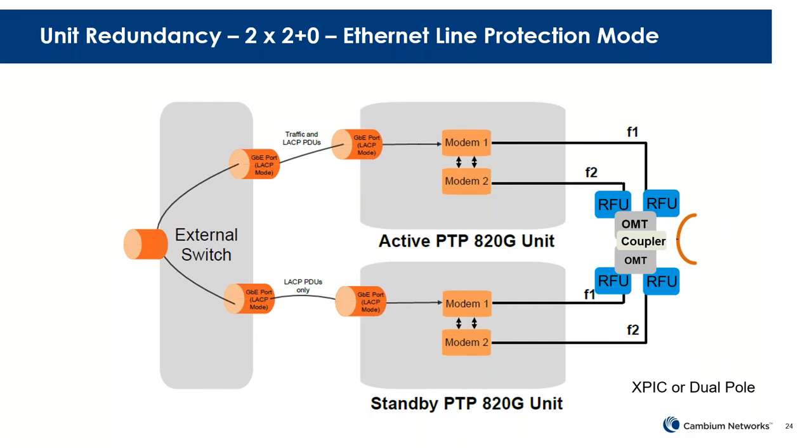I think you need to upgrade everything to have a stable link deployment. I suggest that you upgrade everything to release 9.7, especially for 1+1 hot standby.